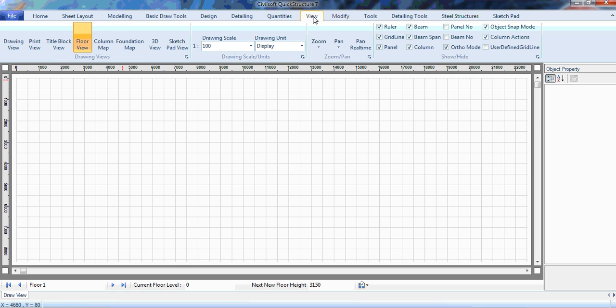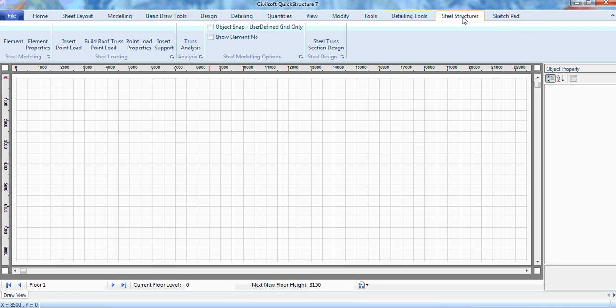All this plays out in the sketchpad view, in the sketchpad tab, but you access that once you click on the sketchpad view, just to tell the software that you now want to work in the sketchpad. And then of course the drawing scale, with this you can always make the drawing bigger or smaller. And then here you can remove orthogonal. If you want to draw an inclined line, of course you can. You can uncheck some other things that you might deem necessary. Then the next of course is the structural steel.